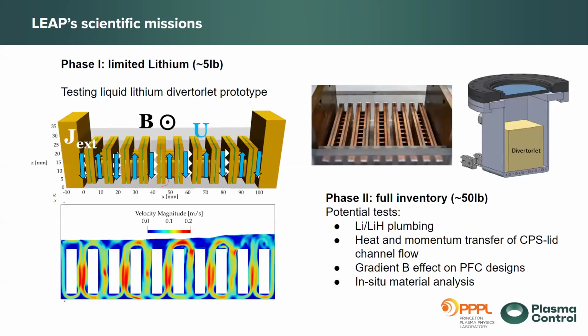You said something about thermal properties. What sort of thoughts do you have for how to heat the surface? Power to the surface, right. If I had an infinite amount of resources, I'd probably use E-beams and plasma heating. But there are also radiative heating methods where you can simulate the distribution of heat flux on the surface. In the least preferable case, but still a proof of concept, you can use a localized heat source like a heater, just focusing on one region of your liquid surface.